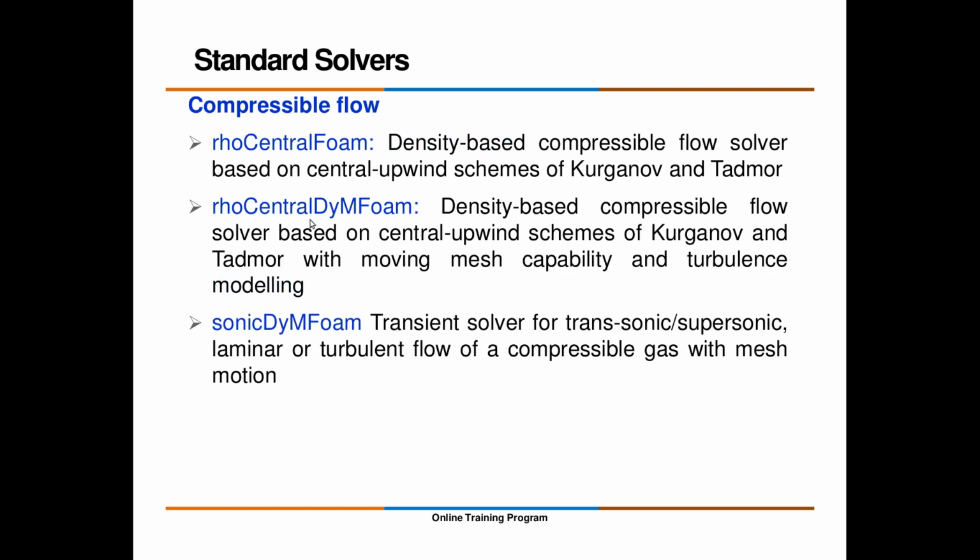rhoCentralFoam comes with a particular class of solver: it is a density based solver. So if you want to build a new density based solver, look, in a compressible environment you work with either a density based algorithm or a pressure based algorithm. If you are working with very high speed flows, sometimes the density based algorithm facilitates much faster convergence as compared to the pressure based one. So stick to the density based type of solver.